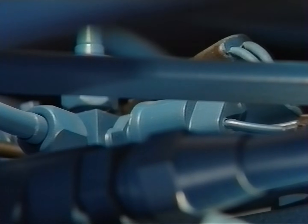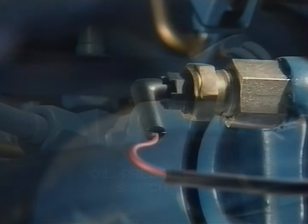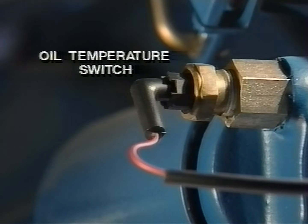The EIP monitors conditions in the transmission in much the same way it does in the engine. On a TW tractor, the transmission oil temperature and pressure switches are located on the right-hand side of the tractor. The oil pressure switch is located in the dual power hydraulic line at the upper edge of the transmission, and the oil temperature switch is in the hydraulic pump cover. Both of these switches operate in the same manner as those we've already looked at, but the oil pressure switch is normally closed and the oil temperature switch is normally open.